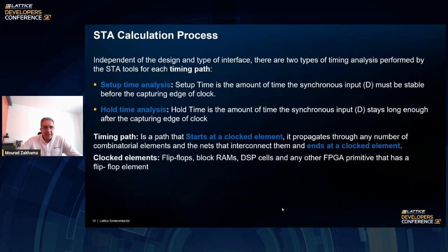So what is the STA calculation process? It's independent of the design. Any design will go through this process. You will have two timing analyses performed by the STA tool: a setup time analysis and a hold time analysis.